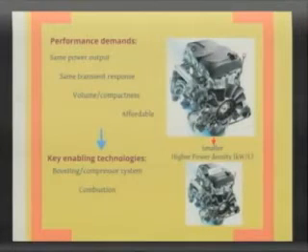And therefore, when I downsize, a key enabling technology, rest assured, coming from me, is boosting and turbocharging. Because, of course, you need to bring more air, combust hopefully less fuel, because I've got less friction, to achieve the same output. Bring more air, combust a little less fuel than I had to before, produce an output which is the same as before. And that is the technology behind downsizing. We are downsizing all engines.